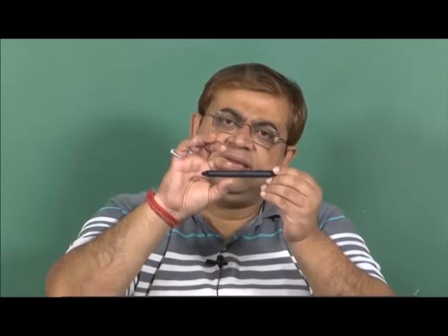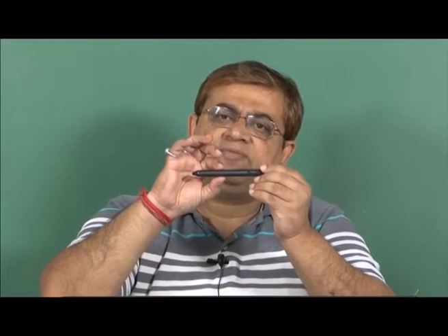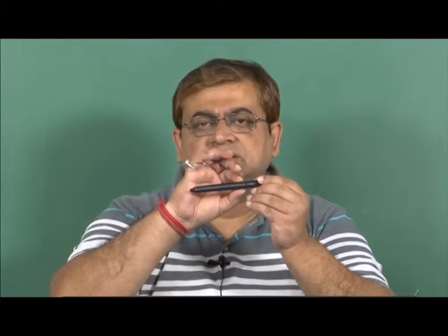So, it is about a traveling contractile. Let us say if we had a flexible pipe and we are creating pressure on a certain area of that pipe, so that the pipe contracts, and then move that contracted area forward in a continuous manner, then obviously the pipe being filled with fluid on both sides of this contractile would have fluid getting displaced in the direction of travel of the contractile, whereas as the contractile moves forward, the space that it creates at the back would have again a pressure difference, because of which there would be flow into the region which is just at the rear end of the contractile.